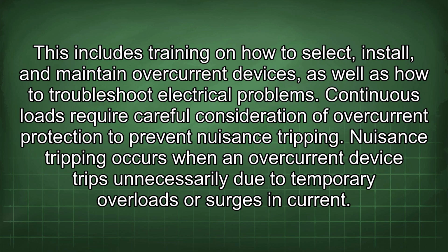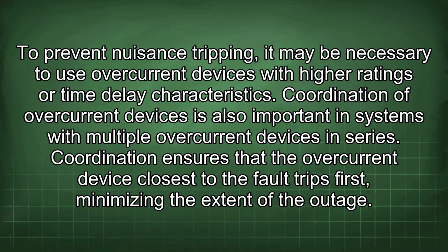Nuisance tripping occurs when an overcurrent device trips unnecessarily due to temporary overloads or surges in current. To prevent nuisance tripping, it may be necessary to use overcurrent devices with high ratings or time delay characteristics.